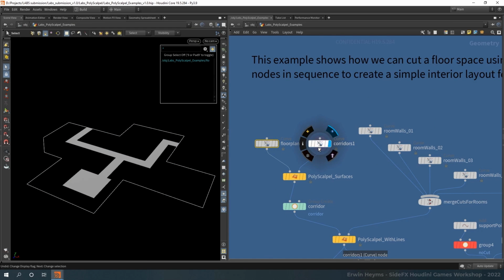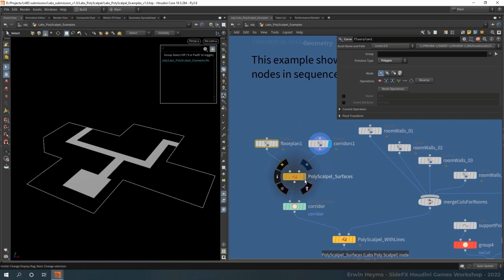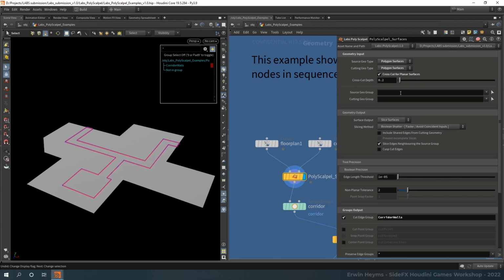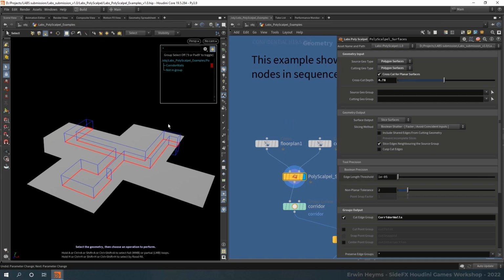These are two meshes. They are basically polycurves, right? I overlap them, and I set the tool into cross-cutting mode. And cross-cutting mode allows me to cut using a hull from the original geometry, basically in the cross direction of the geometry itself. And it will then cut the other geometry with that.